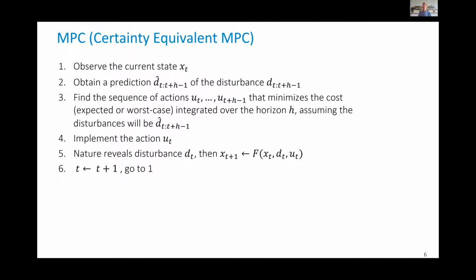Of course, this prediction may be wrong. It may be 20% or even 30% less than what we had predicted. There may be unanticipated clouds, but certainly in the evening there will not be any sunshine after the sun sets. So there is this first order information that is easy to capture, for example, in the case of solar panels. Same thing for temperature. We can have an idea that usually the night is cooler than the day. So we can have even a raw forecast, and that will help the MPC.